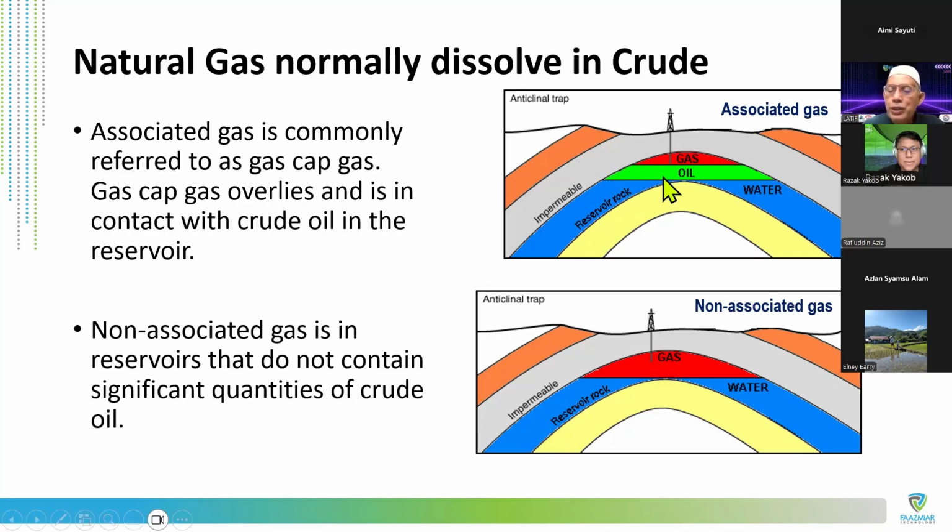So the reservoir pressure starts to get less, but since the water volume is big, coming from a big reservoir, the water system pushes the reservoir to keep a stable pressure, and the production will be much more stable over time. So that's the advantage if we have a water drive system.